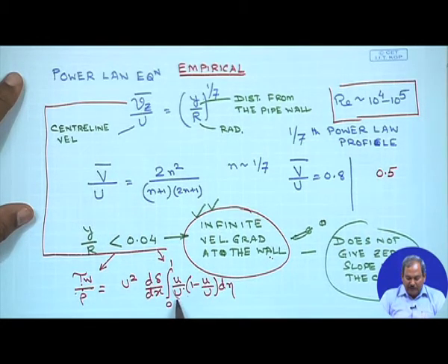On the other hand, the right hand side essentially denotes an integration over the velocity profile. So, the 1/7 power law is an ideal candidate to be used on the right hand side of the momentum integral equation.